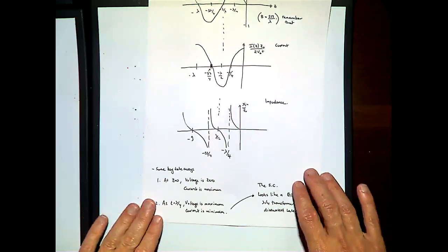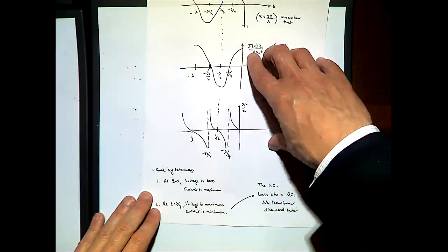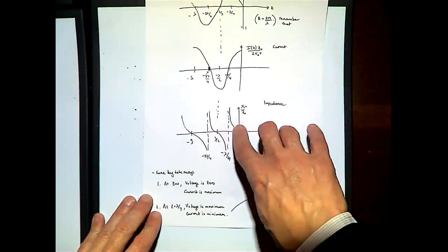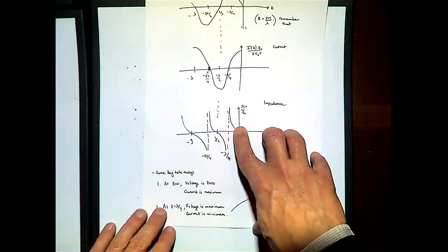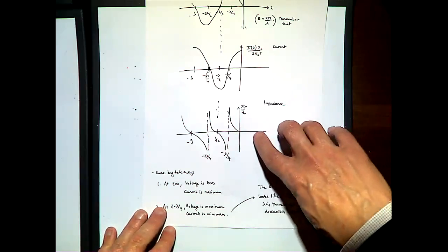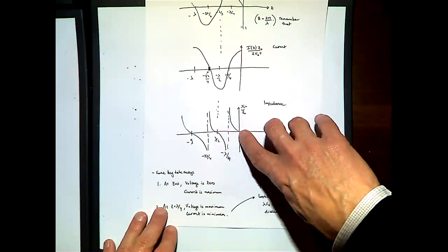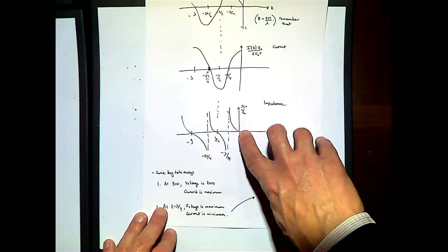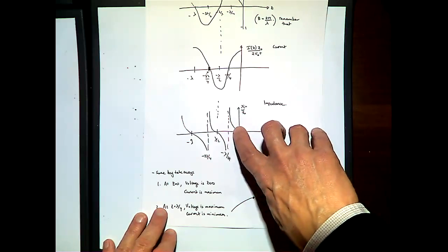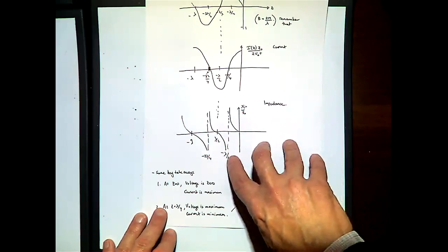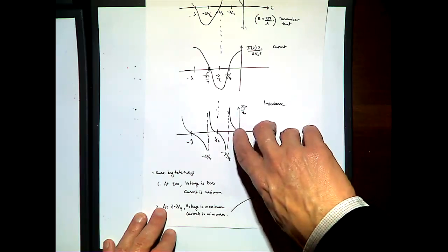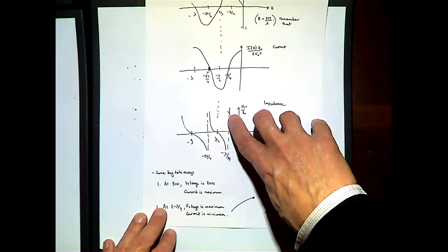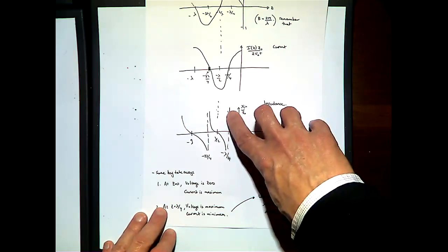Now, what I've done, of course, is then worked out the ratio of V versus Z, which is essentially just the tan beta Z. And what you can actually see is, when you're at the load, the impedance is 0. As you're moving further away from the load, going towards a quarter of the wavelength, the impedance is getting larger and larger, asymptoting to infinity.